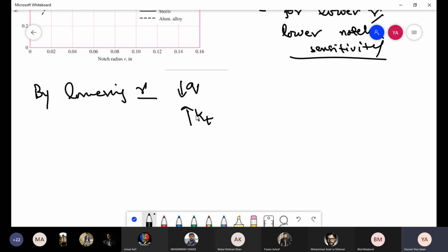That is the geometric effect of stress concentration, and generally this effect is much larger than the effect of Q. So you would not be better off by lowering R, because ultimately the Kf would still increase because of this Kt increase, even though Q is reduced somewhat.